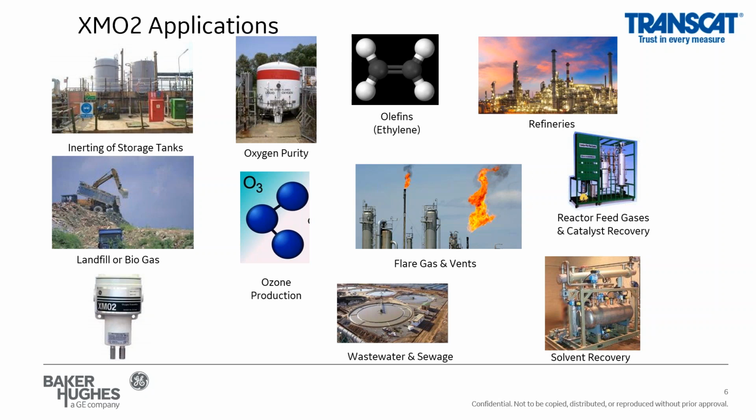In wastewater, when you're trying to break down sewage or waste, there are two methods. One is anaerobic digestion and the other is aerobic digestion. Anaerobic means without oxygen and aerobic means with oxygen. So you would be enriching that waste product with oxygen to help the microbes eat up the waste in the aerobic. And in solvent recovery, that's another application. Of course, the solvent vapors in the presence of oxygen is a flammable or explosive hazard.